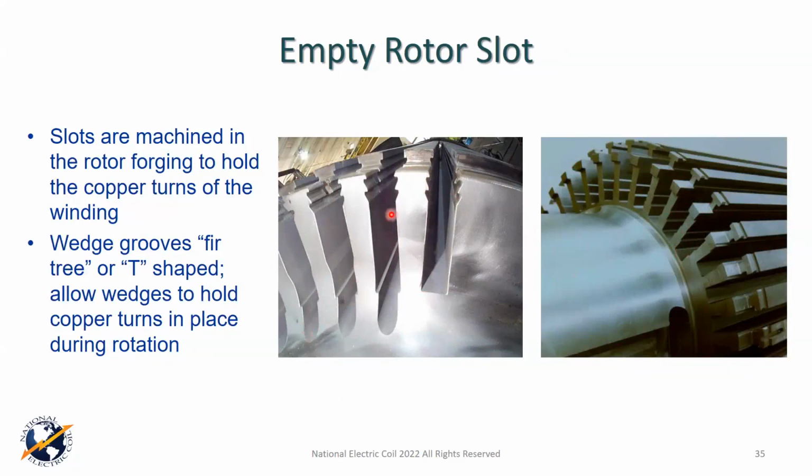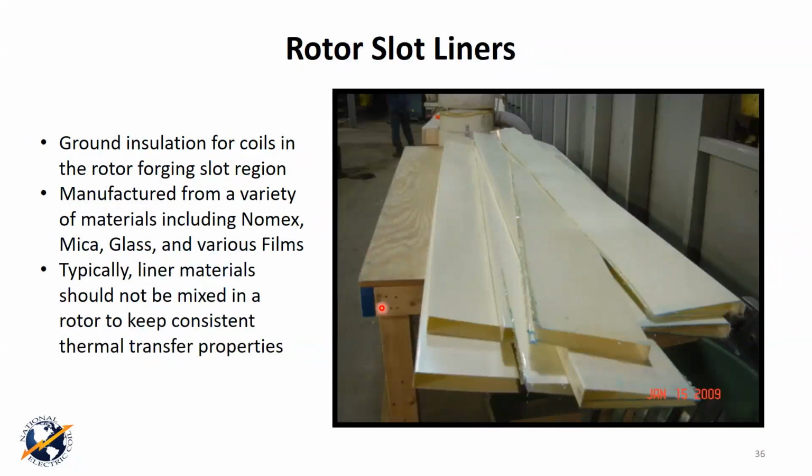In this design over to the left, this is the fir tree design. And you'll see that it's got this channel down here at the bottom on 2, 3, 4, and on out. This is designed to allow the gas to go under the coil stack so it can be exhausted up through radial vents into the air gap, okay? And there's a shelf that's put in here. It's either incorporated on the first turn or it's a material that's put in before the first turn. The first turn would sit on top of it, but it's intended to allow the coil stack to sit above and have that channel remain so the gas can flow down through it. So, that tells you a little bit about the wedging.